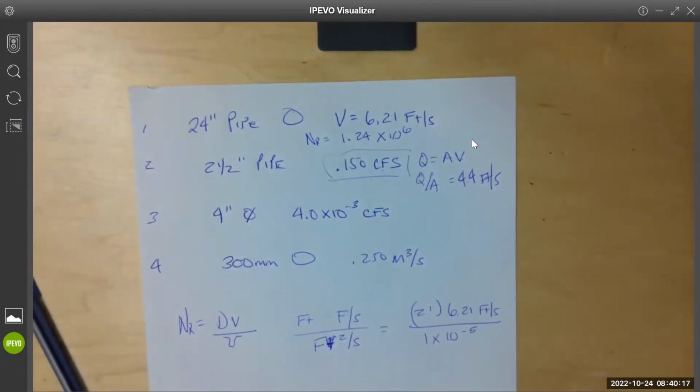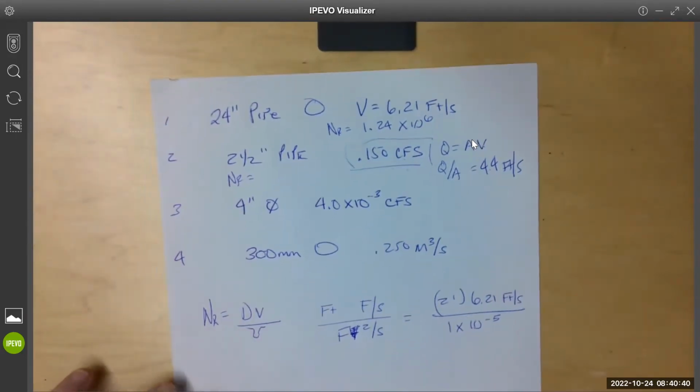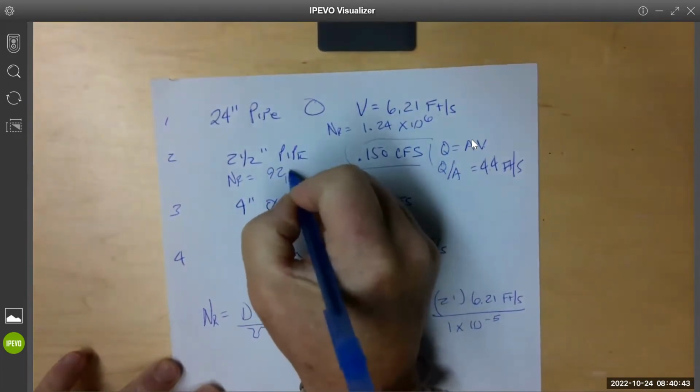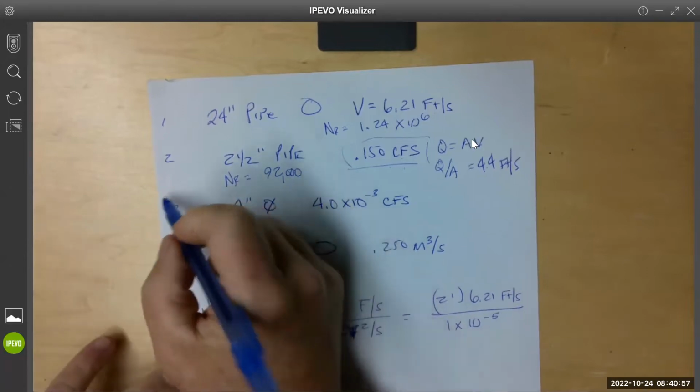Okay. And then same thing, right? Plug it into the equation. Is it water again? Water flowing, it says. So, yep. Goes into the Reynolds number equation. Diameter, velocity over viscosity. And what'd you get for your Reynolds number? 91,702. Yep. Yeah, so since you're comparing to 10,000, just coming up with the number and making that comparison, this is also turbulent.